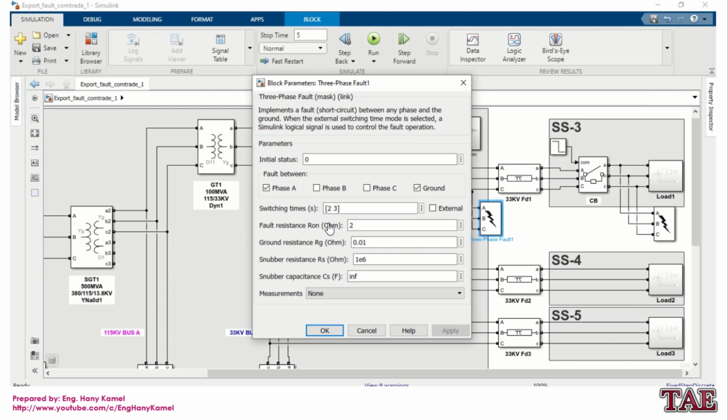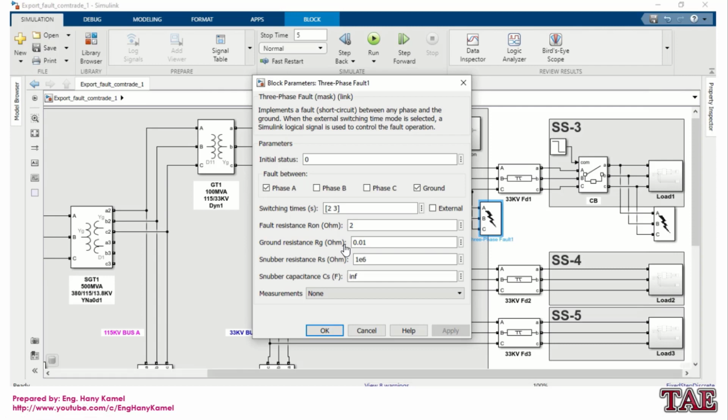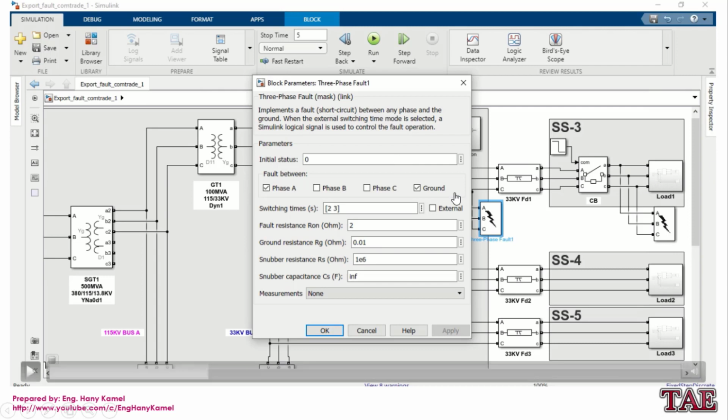As you know, we will take the fault to re-inject again and retest the protection relays. I also make the fault resistance 2 ohms to generate a higher fault. These faults, fault 1 and fault 2, are phase to ground faults.